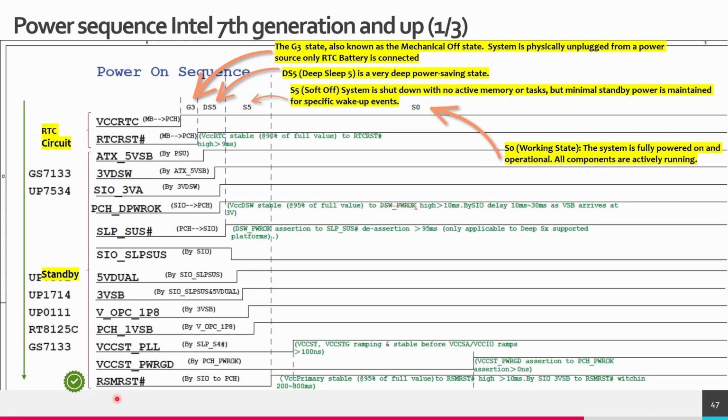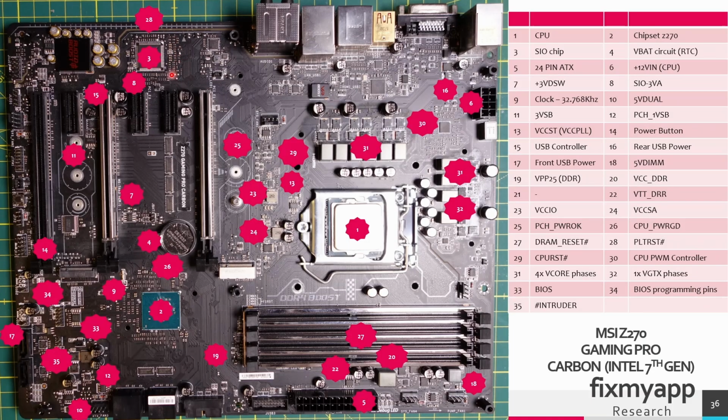to be pressed. So for now, this process is finished, and when this signal is high, so this is the last signal, then you can assume that all the previous voltage rails are okay, and now it's just waiting for an event. The reset master signal can be found at the Super I/O chip at pin 101, and the signal will go to the PCH.